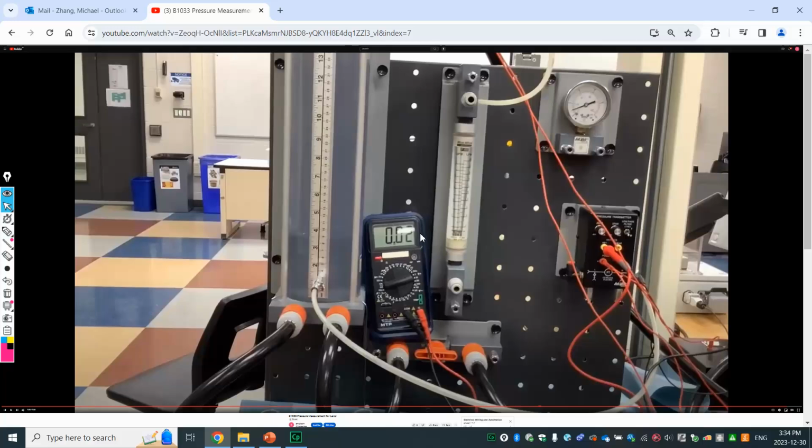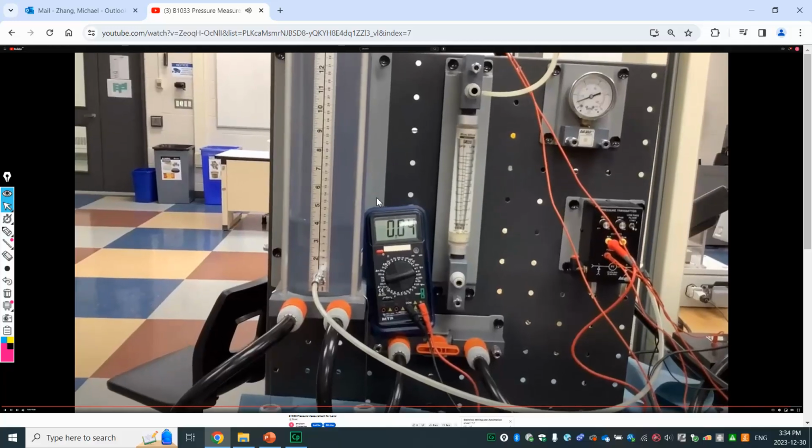One common mistake I see in the lab is that some students forget to take care of the trend. Like I said, if the level is at 15 centimeter, but you already get a very low 0 volt, that's not right. You should start to adjust the zero earlier. So that's what you need to